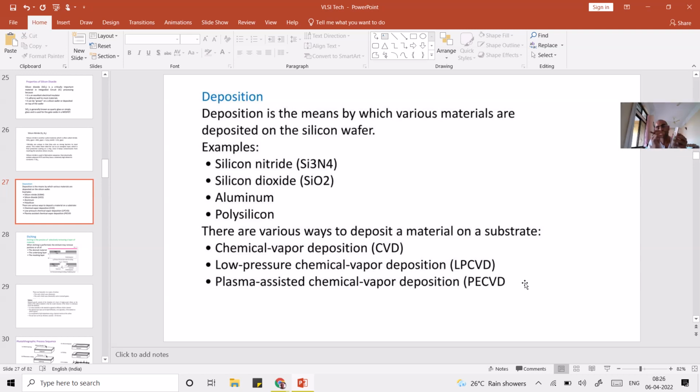This material will start dislodging from that layer, and if it is allowed to settle, then because of gravity itself, if the substrate is lower and you are hitting the material from this region, the atoms will settle down at the bottom surface. So in sputtering, you just hit the material which you want to deposit continuously, and allow the atoms later to settle down on the substrate.